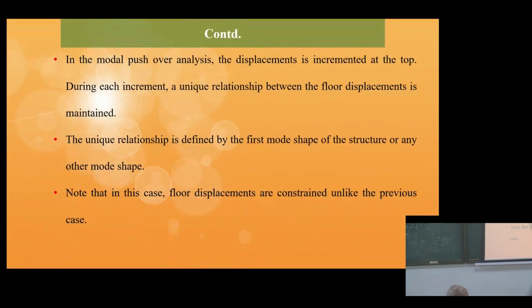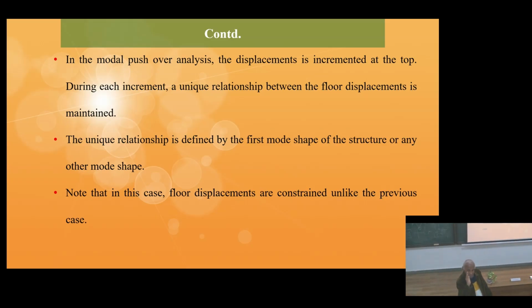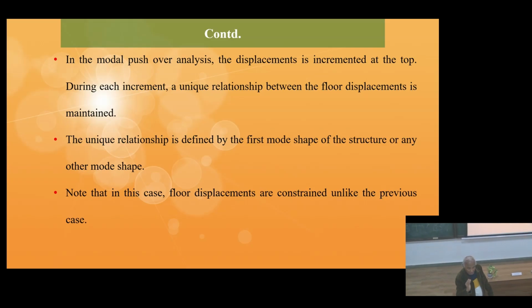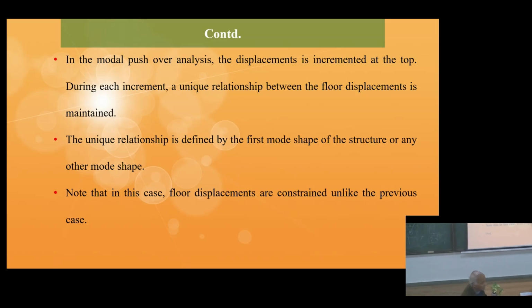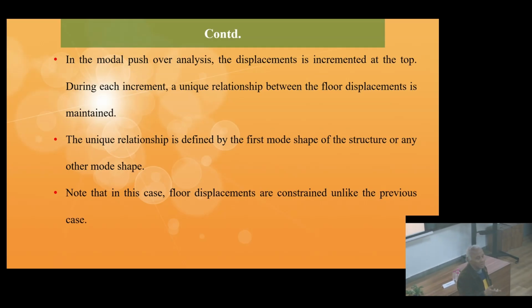Now we straight away come to the modal pushover analysis. And as I told you, modal pushover means that the displacement pattern will have a particular shape, and that shape will correspond to the first mode, usually first mode, but you can make it coincide with any other mode. That's the difference.